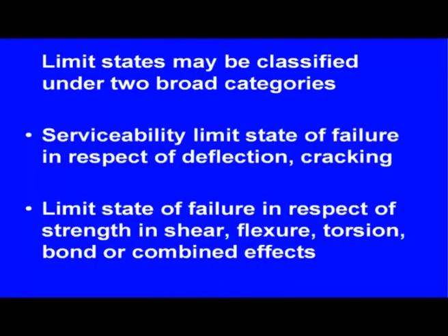We can find out the cement, sand and coarse aggregate ratio, and what will be the corresponding strain? It is true for all grades: 0.0035. For steel, there are different grades of steel. We find it out by Fy by 1.15 plus 0.002.